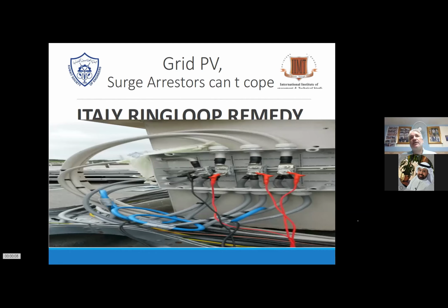I had cases before I energized the system, during commissioning, where we already had between 600 and 3000 milliamps on an earthing ring. Although it was not energized, with no transformer running, a pump nearby with water pipes running next to existing cables was inductively and capacitively coupling into a ring loop earthing, and that ring loop earthing had to be destroyed.